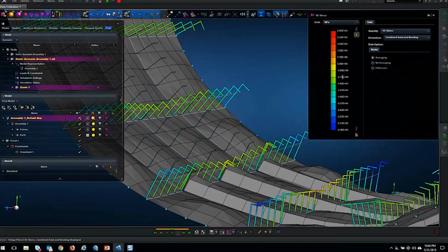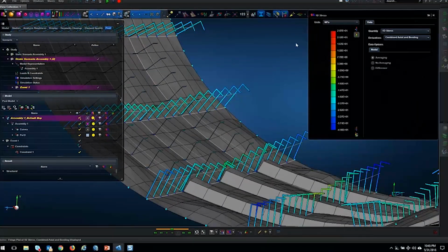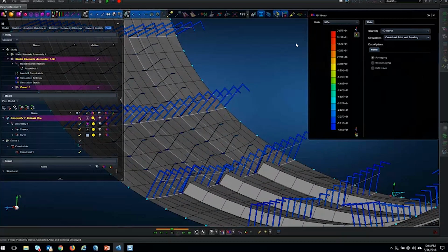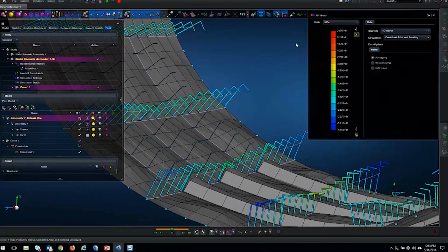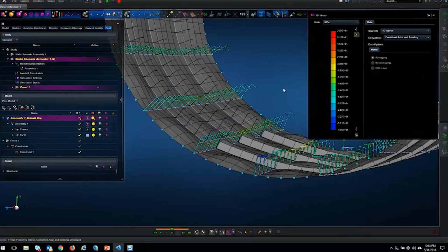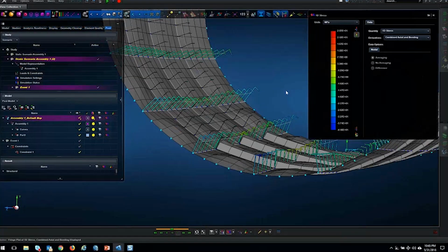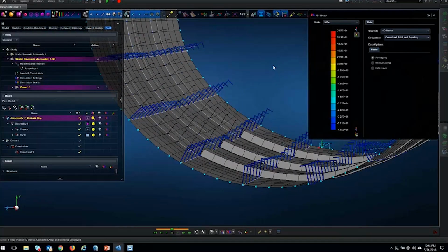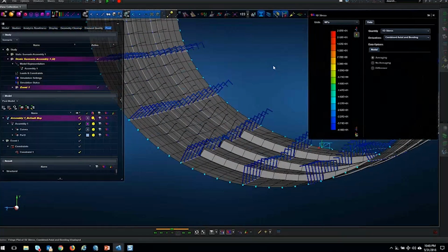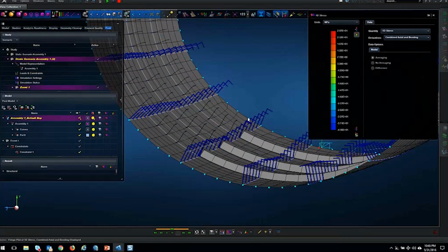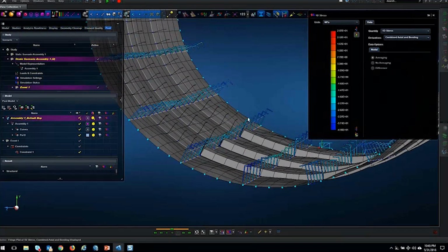Maybe you want to look at the forces through the beams or whatever, right? And the concept of the stiffened panel is mainly because you would like to look at the load-bearing members, optimize the load-bearing members, and optimize the load path so that the structure will bear all the loads that it experiences. Okay, that is what this example is all about.